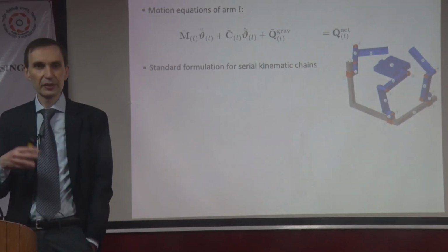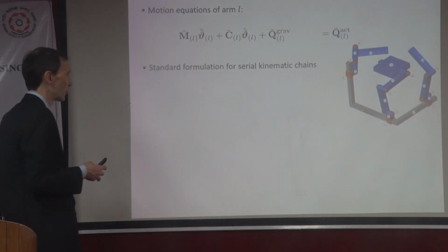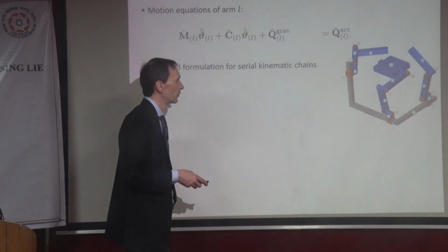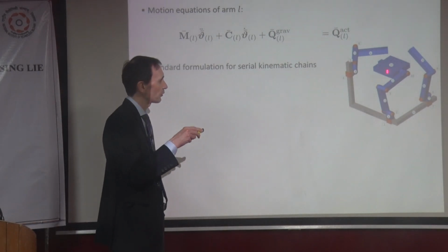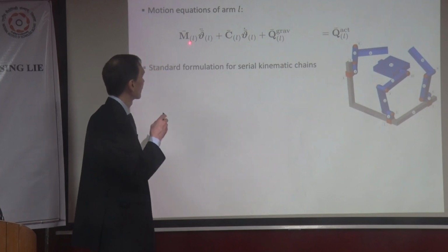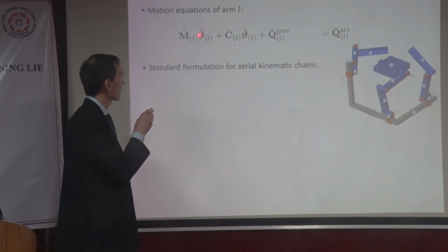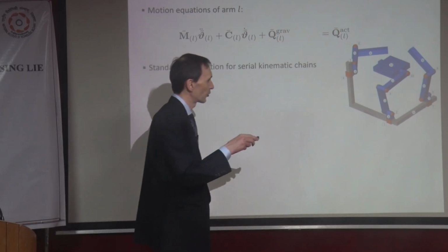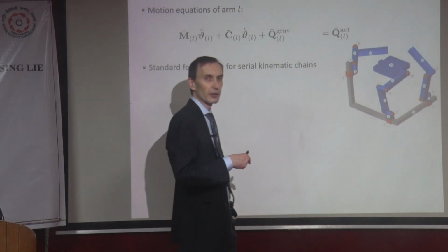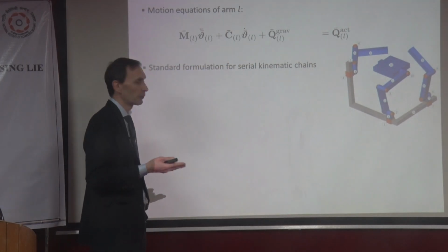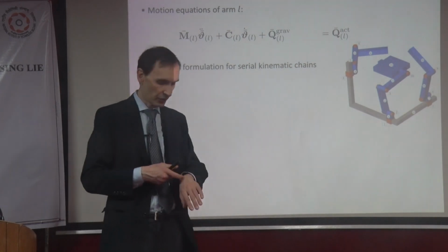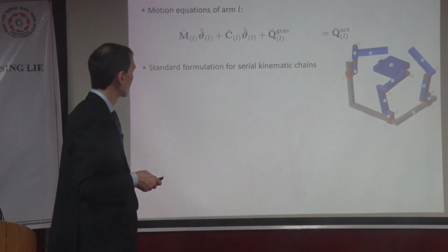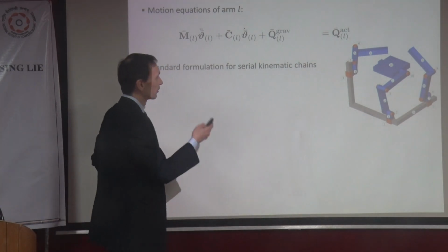I mean, yesterday, and the day before we started doing this, the dynamic motion equations of each of the limbs looks like this. Mass matrix, generalized acceleration, Coriolis term, and the gravity if you want to, and maybe some actuation forces here. Now I would like to assemble it. And again, we talked about constraint wrenches, constraint forces and torques. And we have to include them here, right?